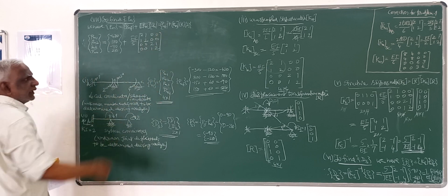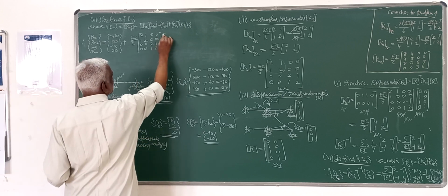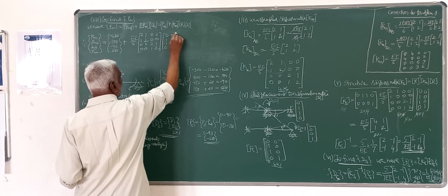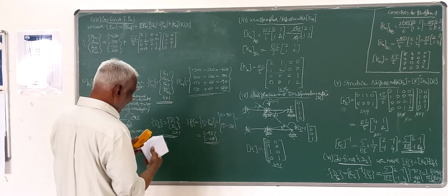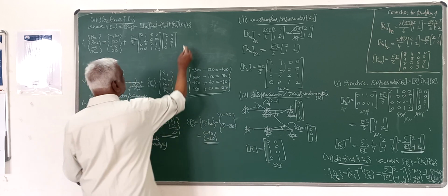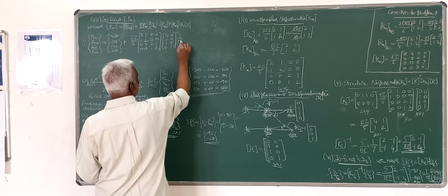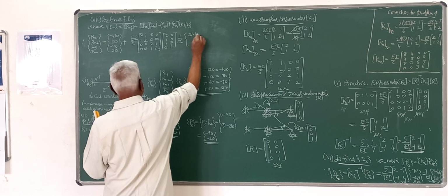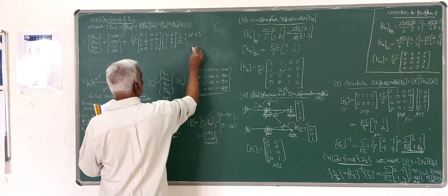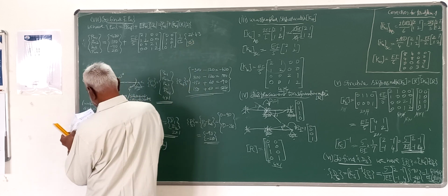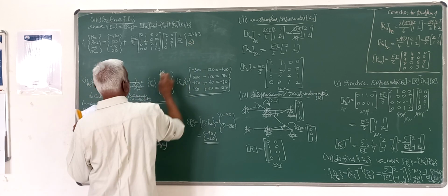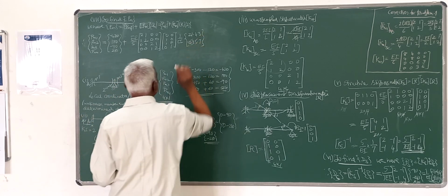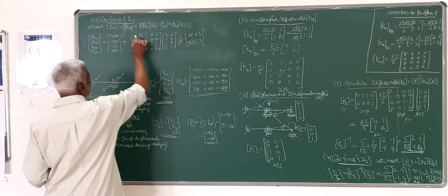That is Km. Then the matrix 0, 1, 1, 0, 3 zeros, 1, r into ds. The ds I have calculated as 1 over EI into 21.43 and minus 535.7. So here I will cancel.